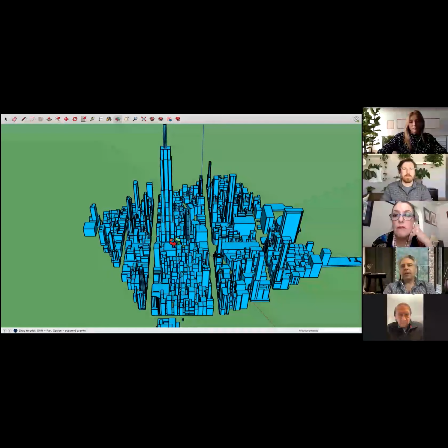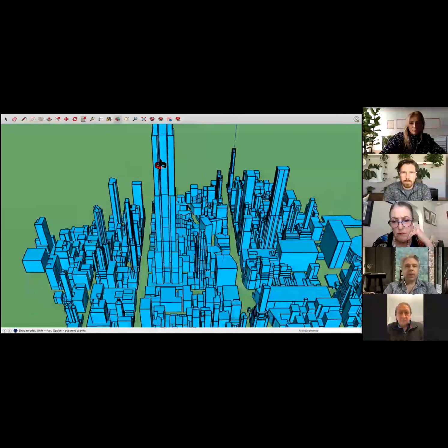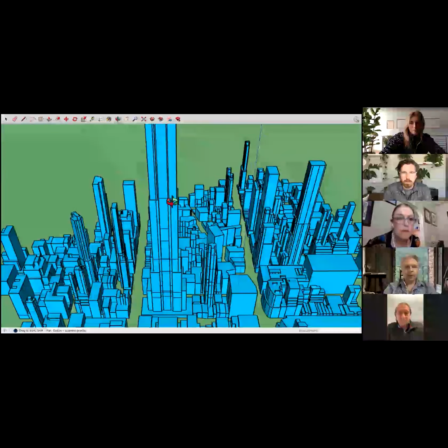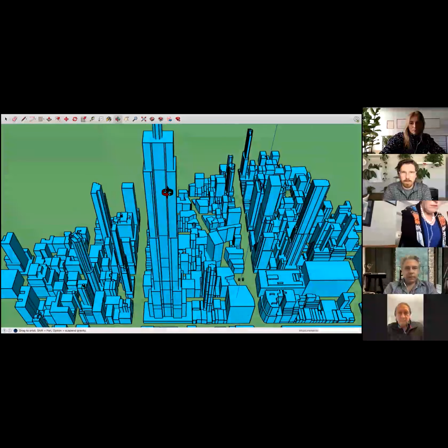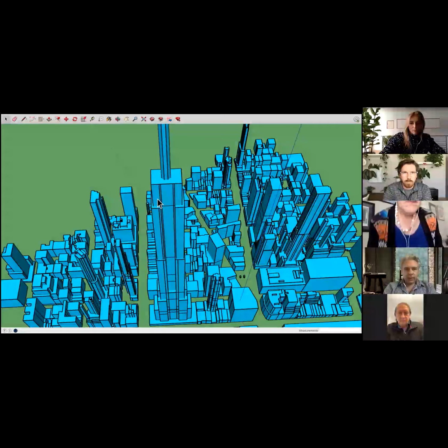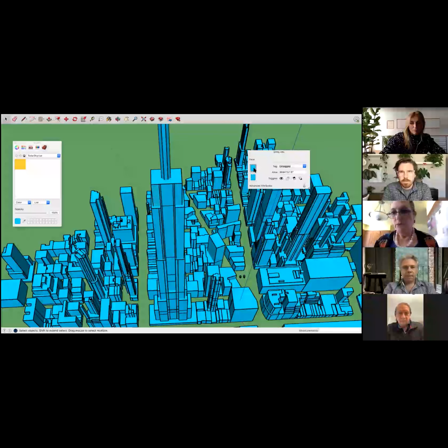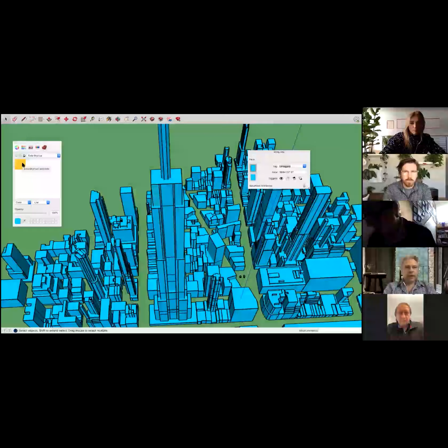Within that new design file, you would be able to add windows and other things and flag them as BIPV claddable using a SketchUp material that we import into SketchUp, and something we'll set up for our clients automatically so it happens. And otherwise within here, we can use this software to go in and actually add claddable surfaces if we want to apply algorithms to clad those surfaces instead of uploading design files. So what we would do in this particular instance is if we wanted to clad one of these facades of the Empire State Building with a material, we would simply right-click on it, get the entity info for that side of the building, drop into this, and you see we have a SolarSkyrise cladded material here.